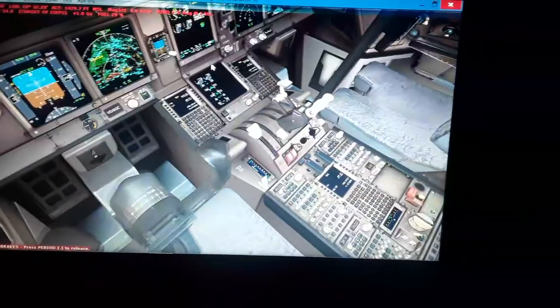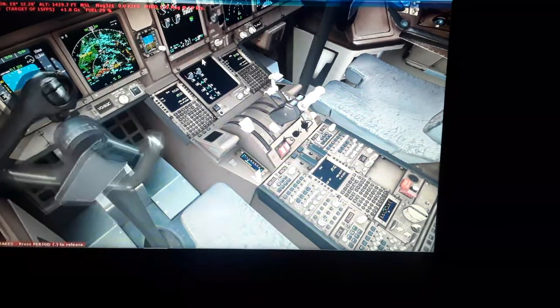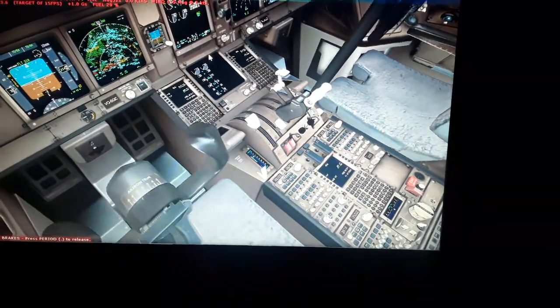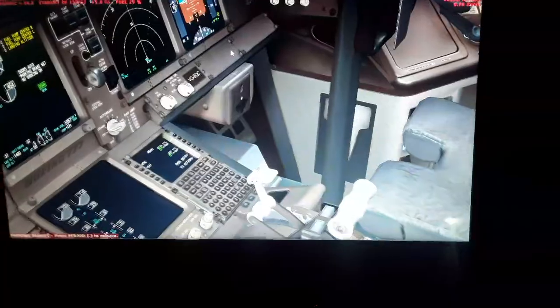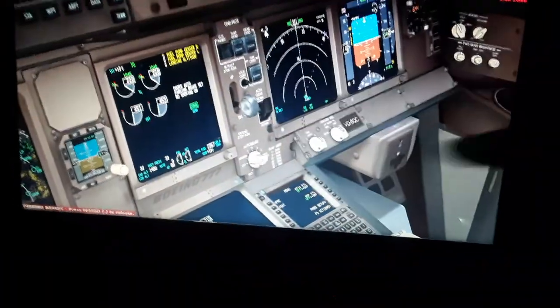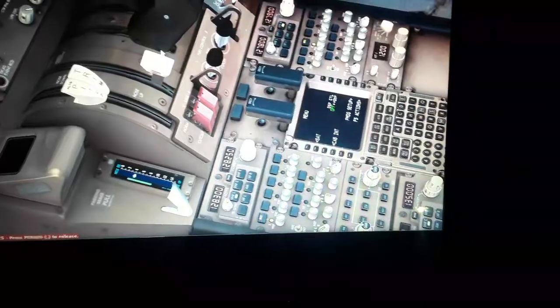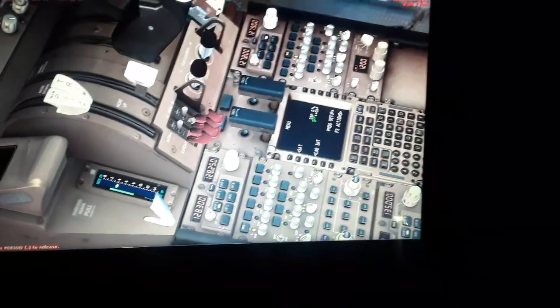You can see here the cockpit we have. You can see the flight controls, the yoke of the Boeing 777, also the rudder pedals. We have the steering wheel here, the tiller for the nose wheel steering. We have the landing gear here. You can see we can extend and retract the landing gear, the auto brakes. Here is the parking brakes. You can see the stabilizer trim cutout switch. This is the electric trim cutout switch for the horizontal tail stabilizer. I'm gonna talk to you later.